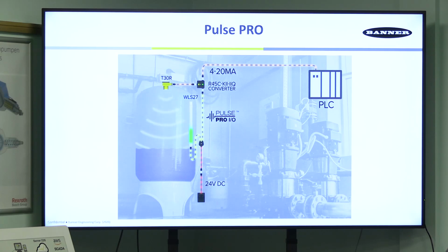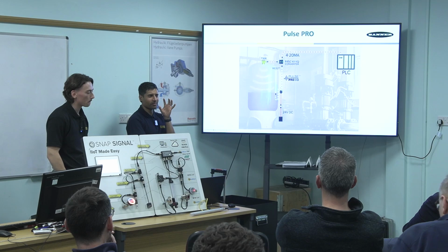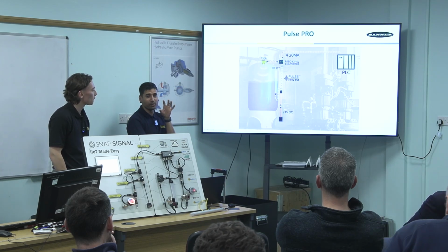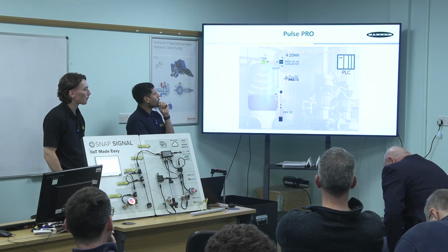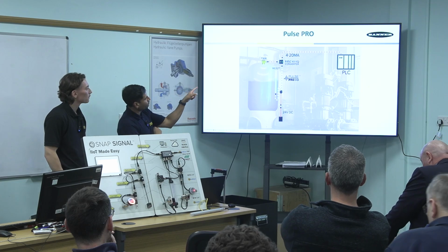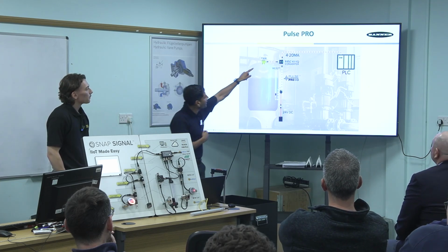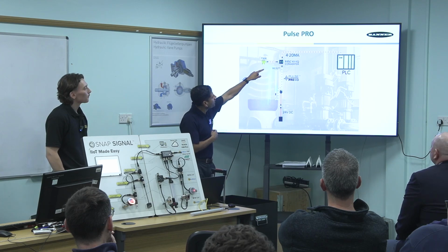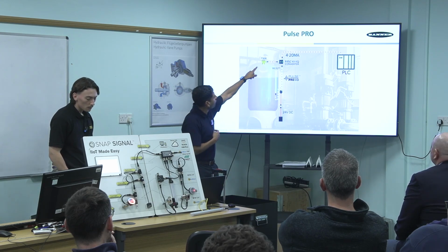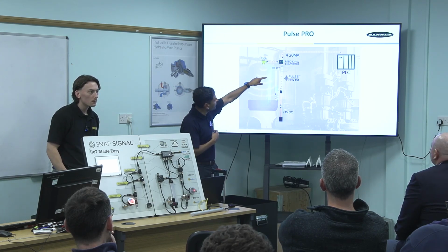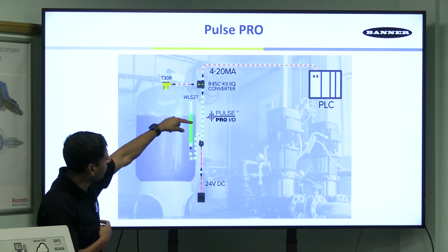Yeah, and we've got some Pulse Pro as well. We're big on visual factory, so it's illuminating your machine basically. And what this is doing, we've got these current converters, so we can take an analog signal out of your sensor and convert that to a pulse output.